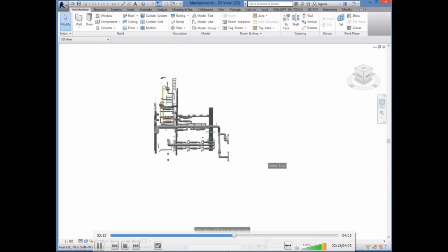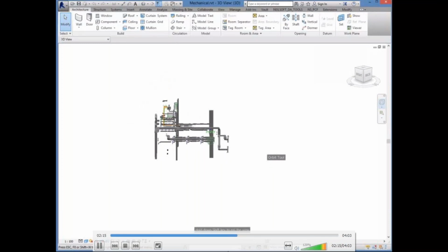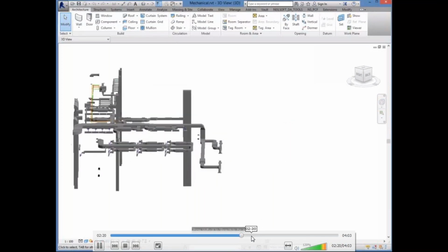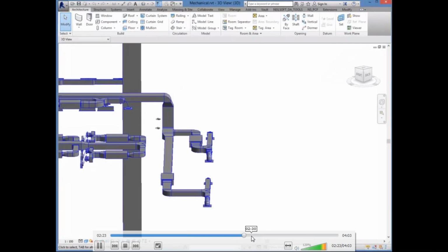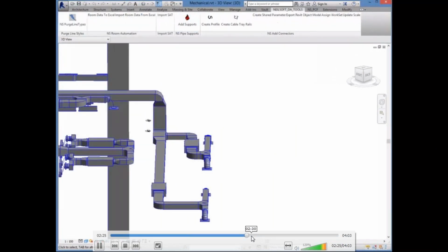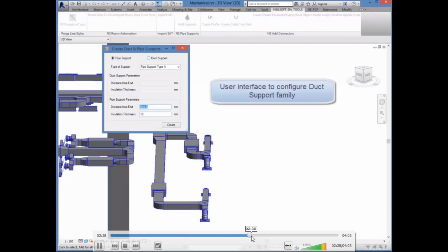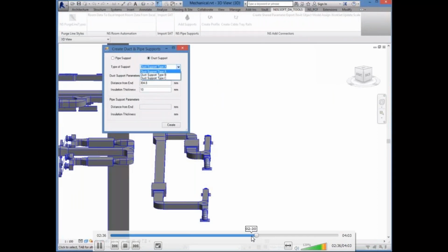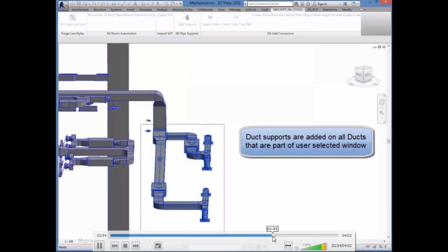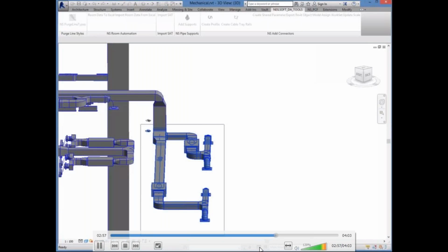So this video now shows the hangers for the ducts. Again, here the duct sizes keep varying at various locations. So every time doing it manually, understanding the size of the duct, adjusting your family instance as per the duct and inserting it, and then doing it over a large area would take a lot of time. But by automating that process, we simply define what needs to be done, just select the position where we want to insert these duct supports, and it would immediately add those.